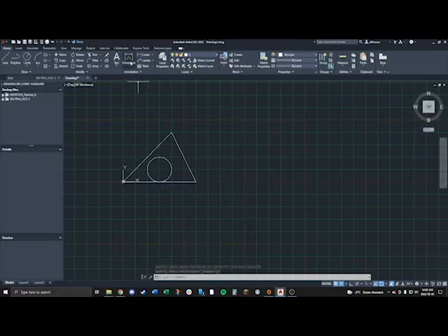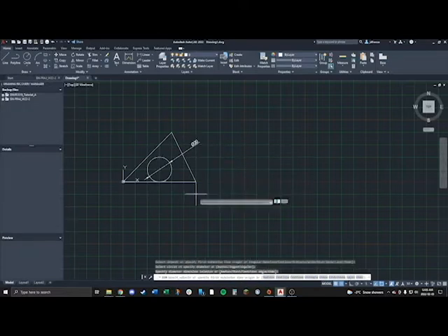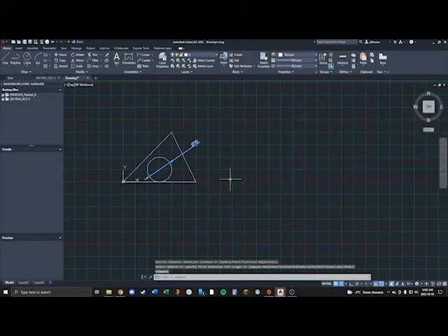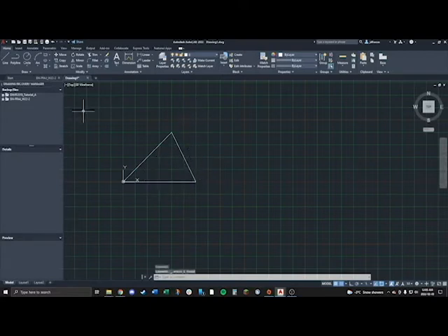And if you need to check the diameter of the circle, you can hit this button, Dimensions. Click on that circle, and it will leave this 20. That will stay in the drawing until you click it and hit the delete key. That's DEL on your keyboard. That will delete it. You can also select any object and delete it, or you can select all of them and hit delete there.